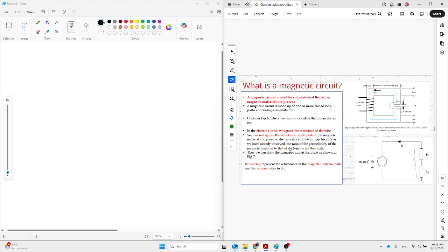and then of course the mu r of this core must be given. Is it given here? I don't think so. The material name is also not given. So usually the mu r is given as, for example, 1000 or 2000, 3000. Be careful about these values. When I talk about 3000, usually you can see different values in different references. But here in electrical engineering, our values are not over 5,000: 3,000, 1,500. Okay, look like that one.